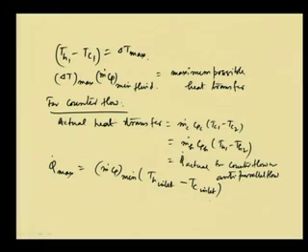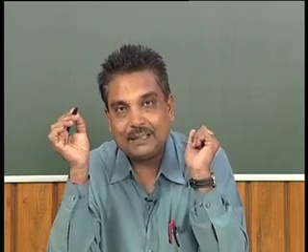So, the cold fluid inlet temperature and hot fluid inlet temperature difference is definitely the maximum temperature difference. Okay. So, based on these combinations, if we have parallel flow, if we have counter flow, and depending on the situations of hot fluid and cold fluid being minimum, we can have several combinations to get the expressions for effectiveness. So, if we write, say, for parallel flow or co-current flow, we have effectiveness epsilon.